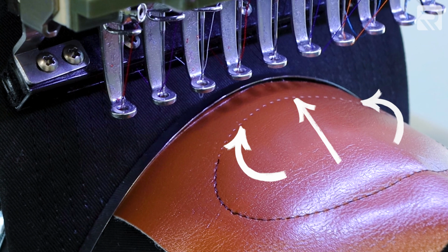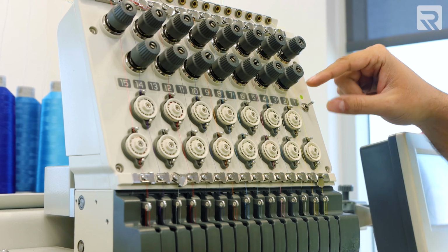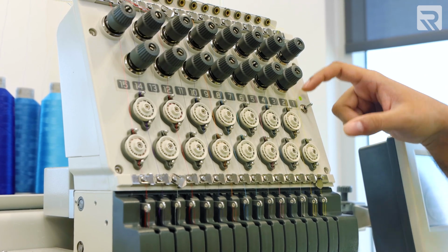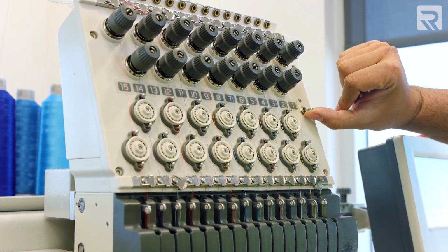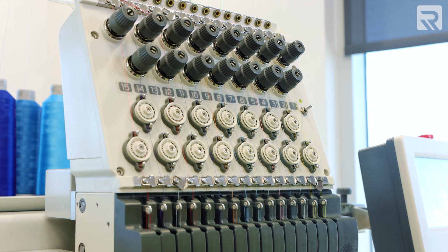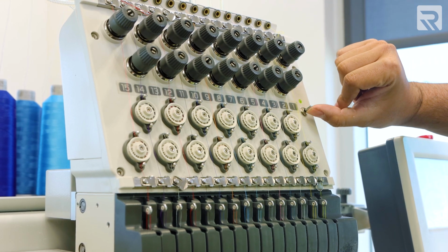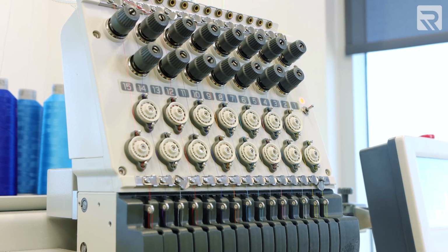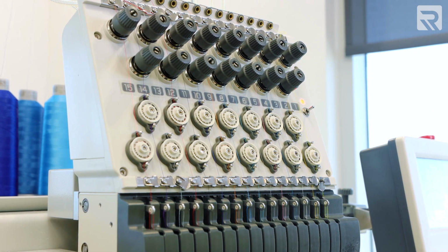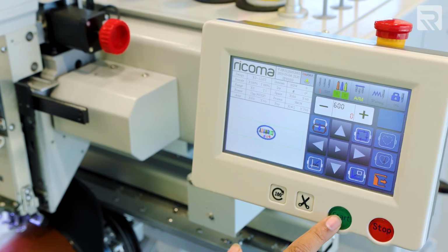All right, so in this case, what happened to me right now is on the bottom of the stitching, some of it didn't register. So if that happens, you can always just go ahead and hold the stop button and it'll rewind for you. So we'll go ahead and toggle the machine head switch. If you toggle it down, it deactivates the head. If you toggle it to the middle, the machine head is on. And if you toggle it up, it gives you the red light indicator. So since I floated back, now I can restitch. So we'll do that now. Let's begin.